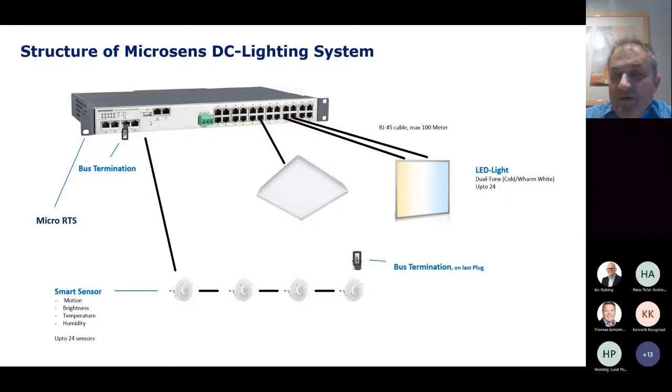In general, this device is a 24-channel DC-fed light controller with an integrated automation platform, which is freely programmable. And next to lighting, you can also run other automation tasks in the room. For example, you can control blinds from this device. If you get information from a third party about wall buttons, you can control over this device also the blinds or the heating control, because the automation platform integrated in this device can get third-party information over the network and process it.